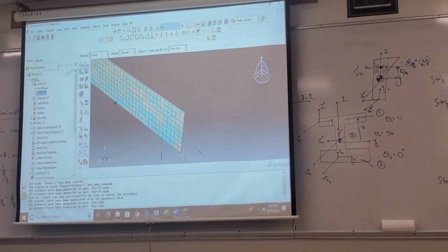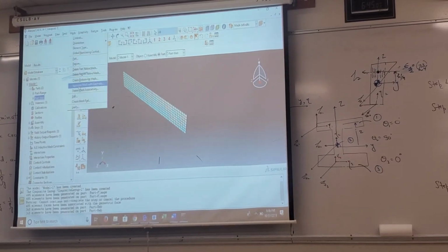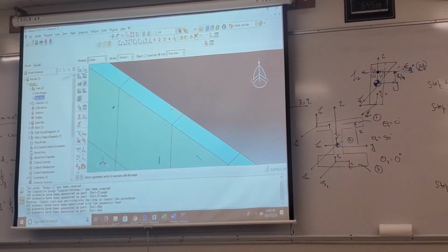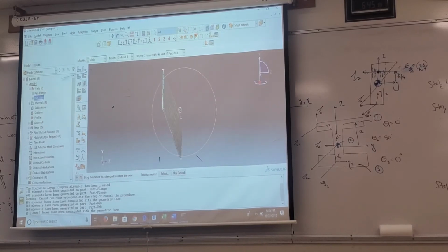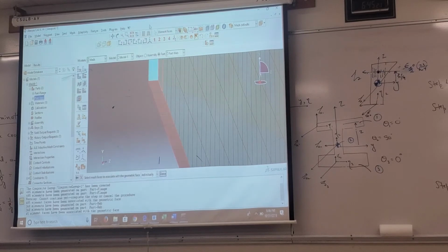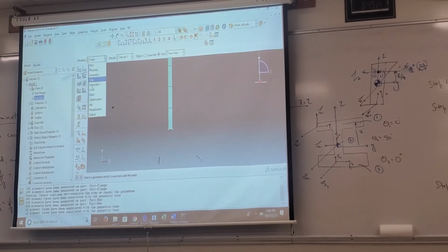The only two sides I need to associate with I'll be using, which are these sides or these surfaces. So I'll select this, deselect that, that's done. Now similarly at the bottom, I will select this, select that. So everything has been defined, so I'm ready to submit the job.